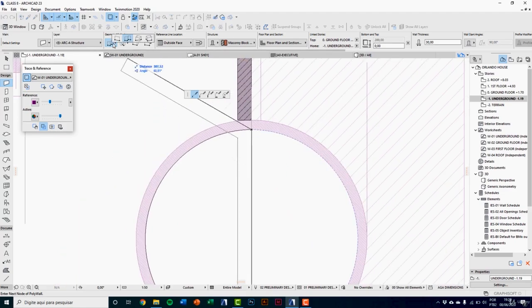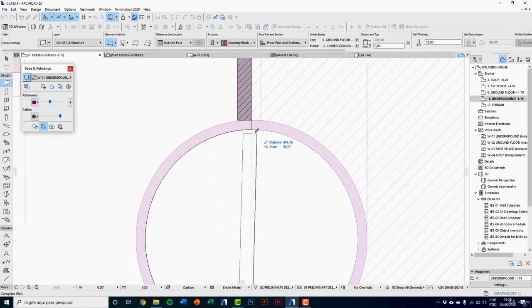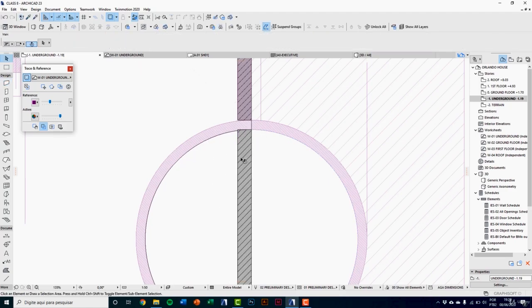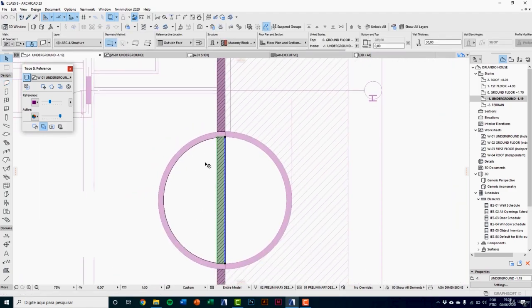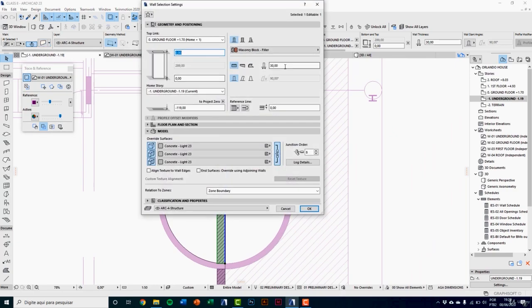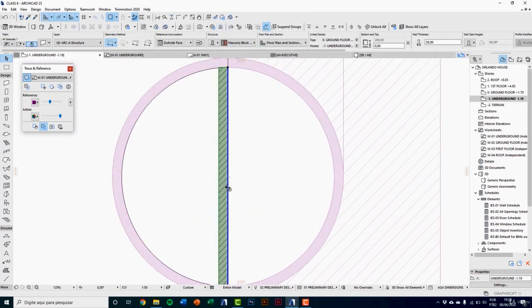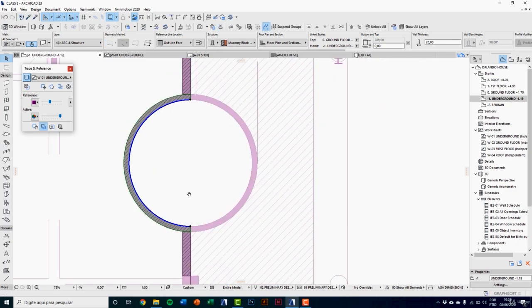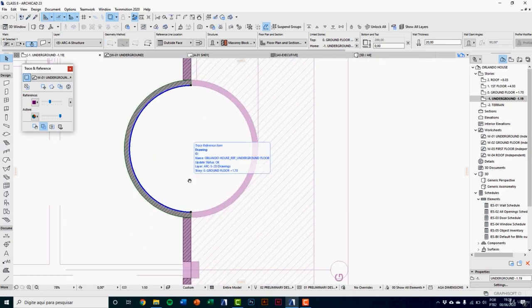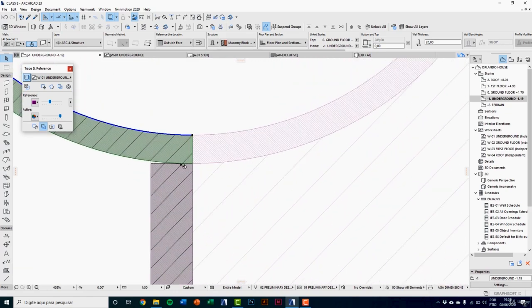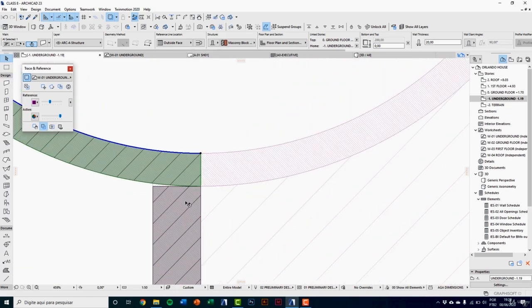here I will change to a simple wall, basic wall. I will select this element. In settings dialog, I change to 20 centimeters width, only in this wall, and clicking on the edge, I choose the option curve edge. And so I can do this curvature. You see that walls are not connected because reference lines are not connected.